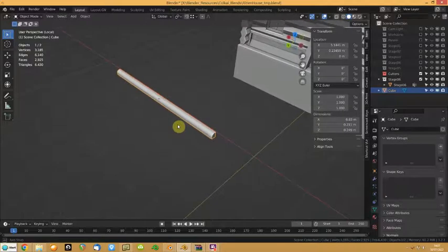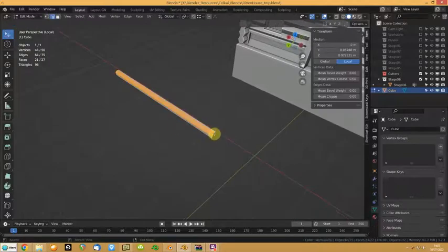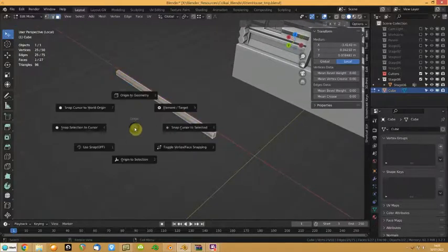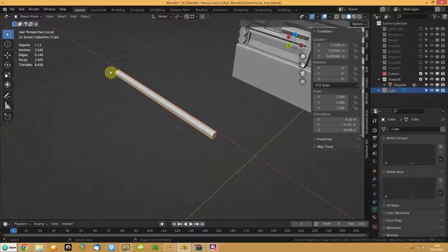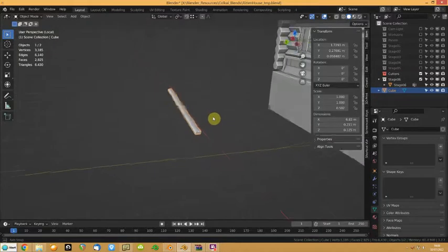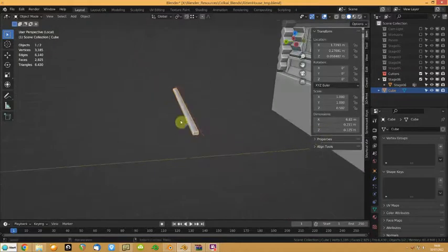And I also do that a lot. So say for example I choose this and I make that my selection. I now want this to be a set length. Now I want it to be 0.225 long, like that. You can see it's adjusted the scale. If I put 125 long, like that, that's on the Z. So I'm just going to undo that.